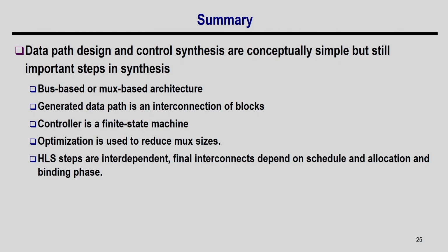So, in this class we basically discussed the data path and controller synthesis. Although conceptually the steps are very simple and very conventional, it is a very important step. Without that we cannot realize the actual hardware, right. And also we have seen that this interconnection can be bus based and mux based. For bus based, your optimization objective is to use the minimum number of buses as well as switches for the interconnections. For mux based, you try to reduce the mux size and hence the controller size. Okay. And then once you have this interconnection ready, your controller will be represented by a controller FSM.